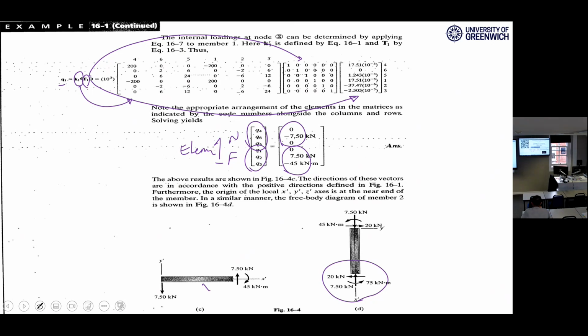But if you insist on this method, if you insist to have them in a matrix notation, you need to make nodes there where you are interested to calculate that information in the first place. So it will change your stiffness matrix somehow. It's a kind of compromise. If you want to add some points, you will get a bigger matrix, but that's fine. If you do that, you will get exactly those numbers in your calculations when working with stiffness matrices, right?